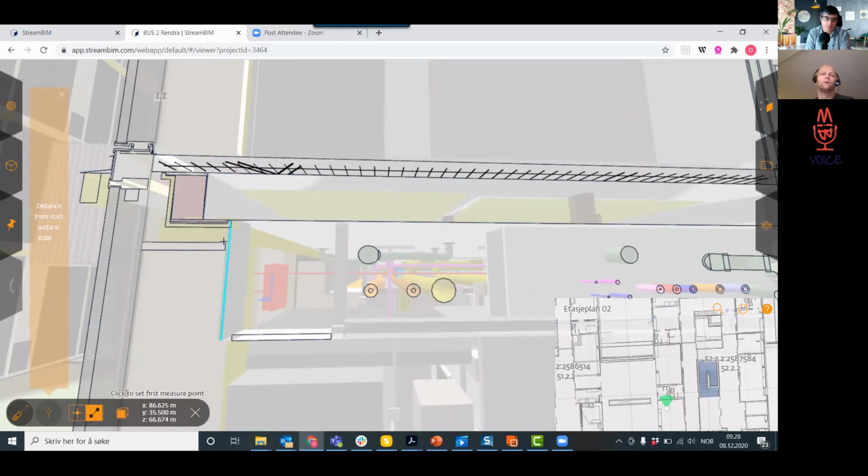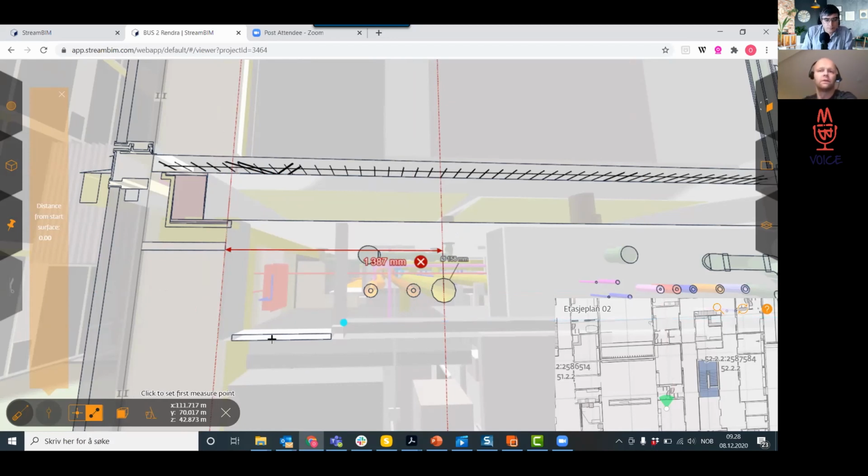If you hit either a line or a corner, in this case it's just the edge here, start there, it will only take the horizontal line to whatever you hit when you move the cursor over objects. So you can continuously see distances that you're measuring to. And then if you want, you can place the measurement by just clicking it out. So that's how it works.